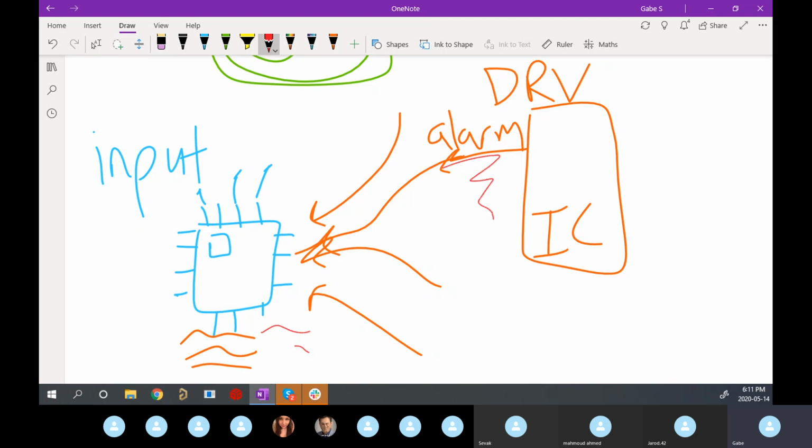If all of a sudden my pin tells me, hey, you've changed state, now there's an alarm on your input, then I can know to shut down the system, stop spinning motors, and stop drawing current from the battery. So GPIOs are a great tool for state checking, right? Where you're seeing, is something on or off? Is something good or bad? Is something on fire or not on fire?